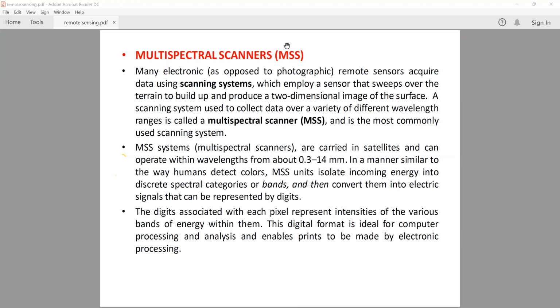What we discussed earlier was: what is the objective of gathering information? If your objective is that you want elevations, you would choose LiDAR. If your objective is that you want to get different measurements, then photography is probably the best remote sensing sensor.